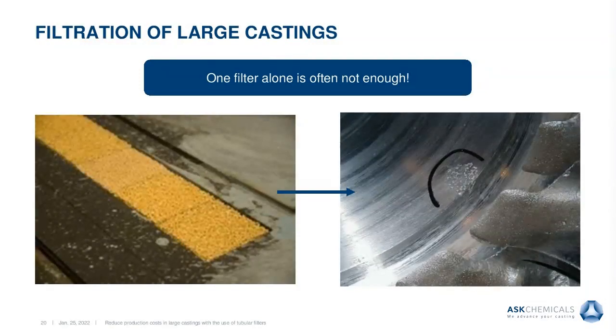The picture here shows a typical installation of many filters in a row. You can see the side-by-side installation without any additional support at the joints. There is no support in the filter bank, in the places between the filters where they are joined together, which is also a risk of filter breakage.